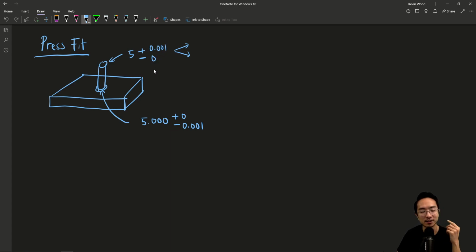And there's actually hacks too if you get a dowel that's not the tolerance you want, like you want it to be a little bit fatter. You could take a hammer and just hit it on the head, and then it'll kind of mushroom a little bit. So those are some hacks you could do. There's also ways you could hack by hammering your plate to change the tolerancing, but that's another story.